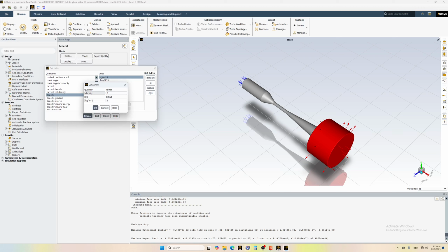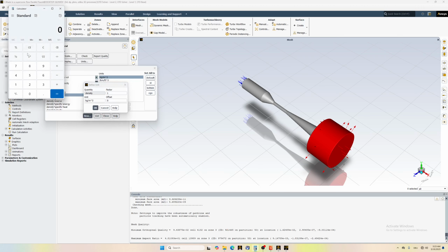For helium the factor is 1 over 15.045, only for helium. If you want to calculate it, you just use the ideal gas law to transform from pressure to density. So it's fairly easy.